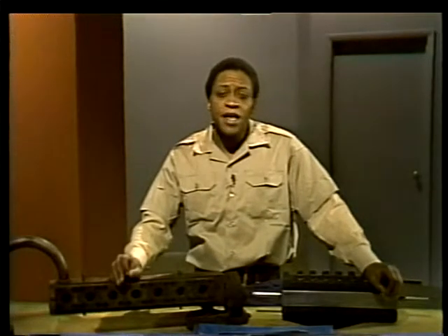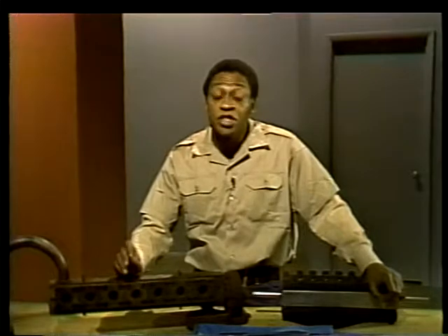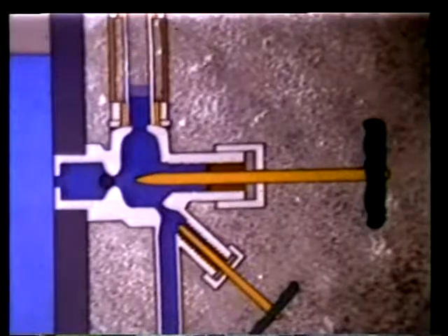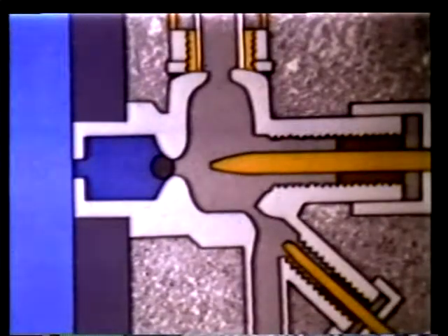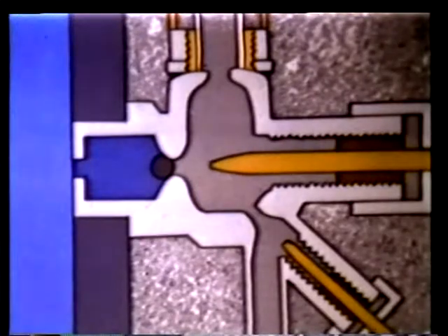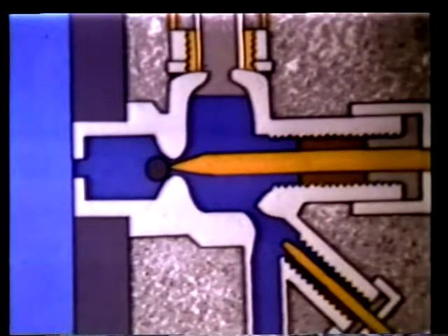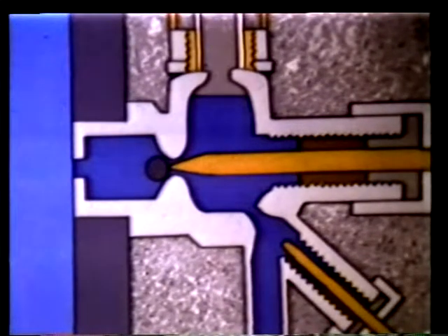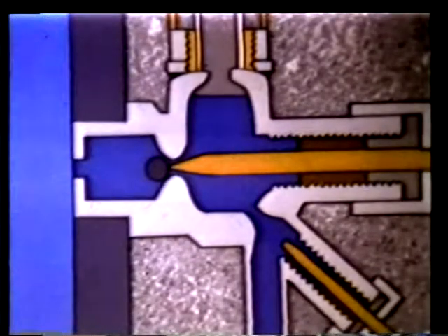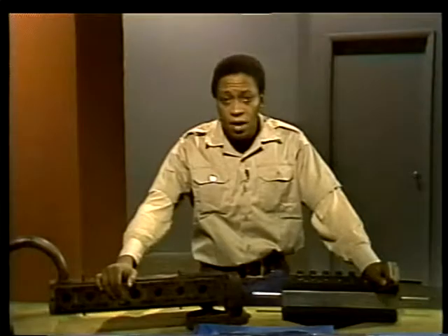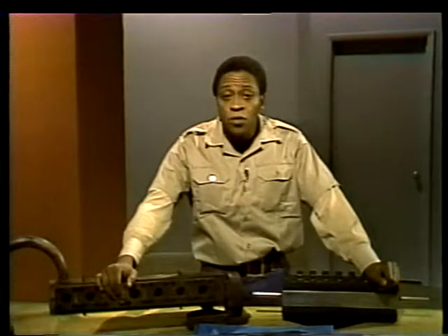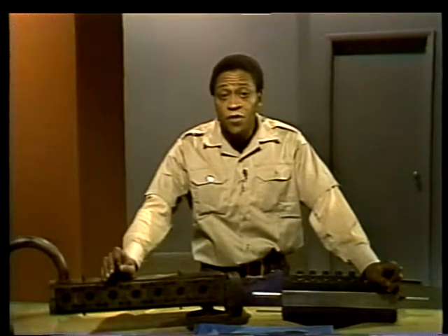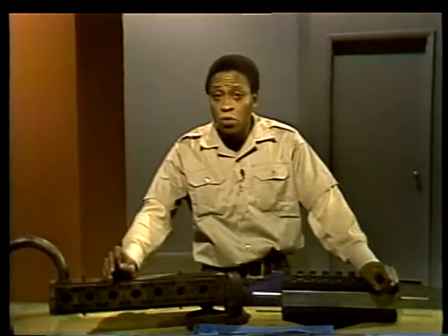However, gauge glasses that have ball checks in their valves are difficult to blow down. The ball check limits blow-down flow. To prevent this, the valve stem has an extension that allows the ball check to be unseated by turning the valve stem toward the closed position. Just before the valve is closed, the extension will push the ball off its seat and open the ball check. This allows the gauge to be blown down through the drain valve. Remember to open the isolation valves when you finish blowdown, or the ball check will not work when needed.